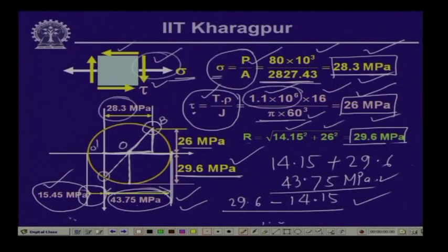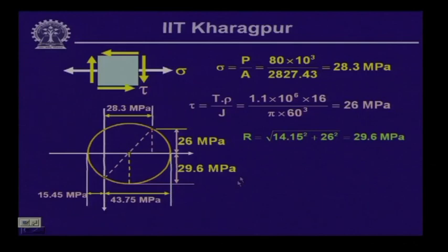So, these are the stresses acting on this particular member, and if you recollect, in the previous lesson we showed you that this type of force distribution or load combination comes in the case of a shaft used in a helicopter fan, which is subjected to a twisting moment, and because of the lift it is subjected to an axial pull as well. So, if we compute the value of the stresses, we get the stress in this form in such shafts.